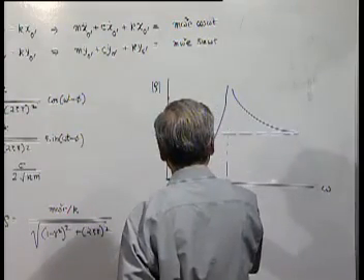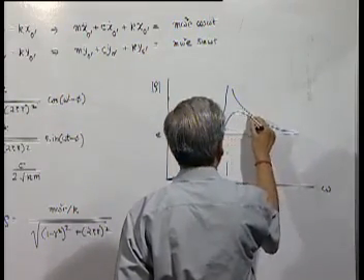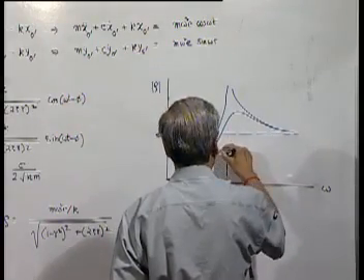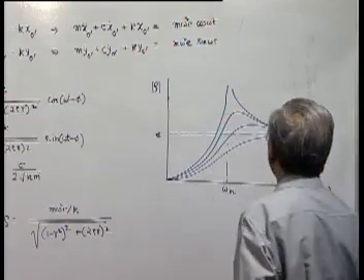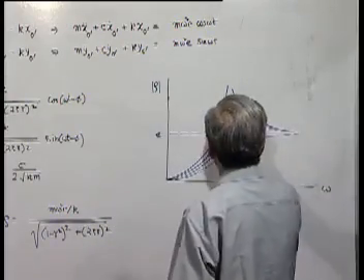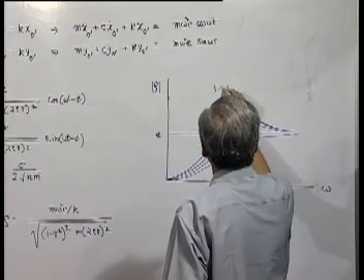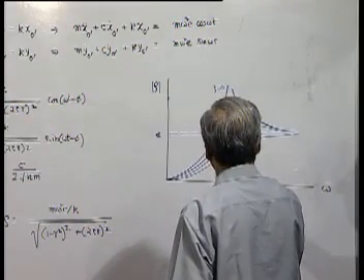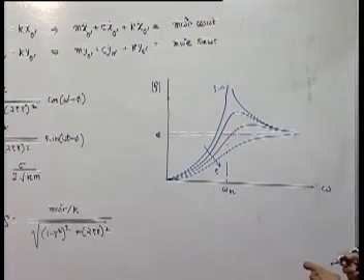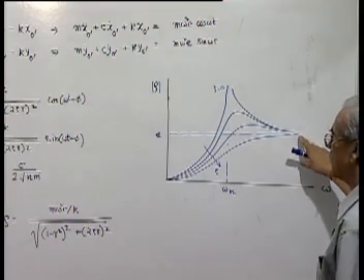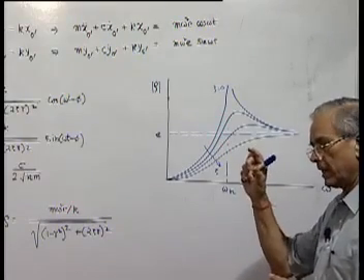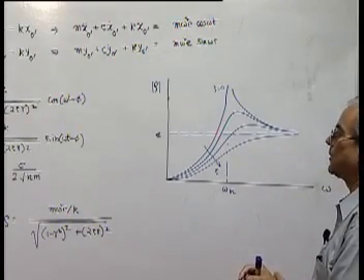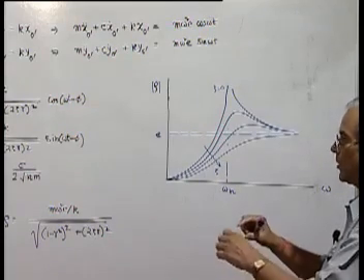If zeta is present, if zeta is increasing, so at very high speed, the deflection of the shaft will be equal to the error of the center of mass from the center of the actual shaft or axis of the shaft.